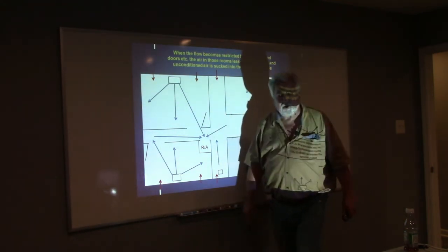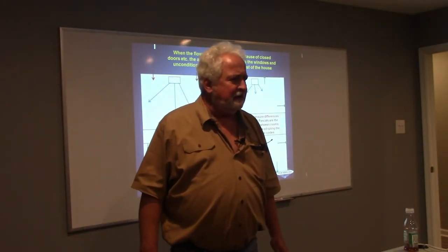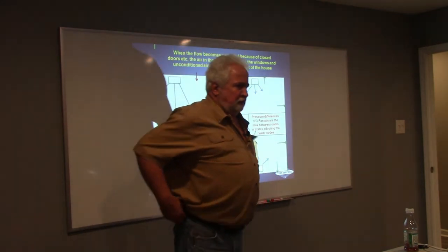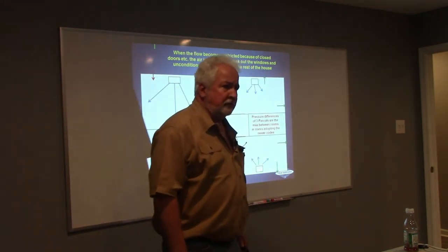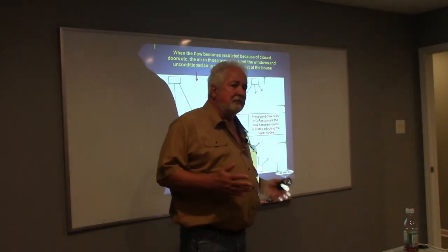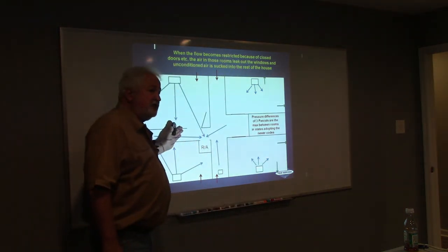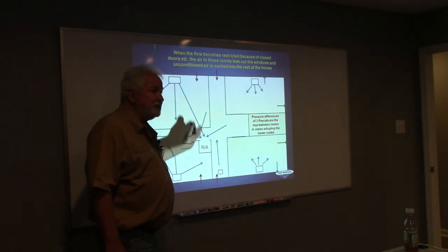And you go over and talk to that homeowner and you say, do y'all close the doors? And what do they say? Never. Oh, no, I never close the doors. How are you going to be able to figure that out? You've got to be able to establish what's going on. Because right now, can they get the humidity level right in their home? What's it sucking in 24/7 that those kids have the doors closed? Yes, 100% humidity. It's sucking in that humidity faster than the air conditioner could ever pull it out.